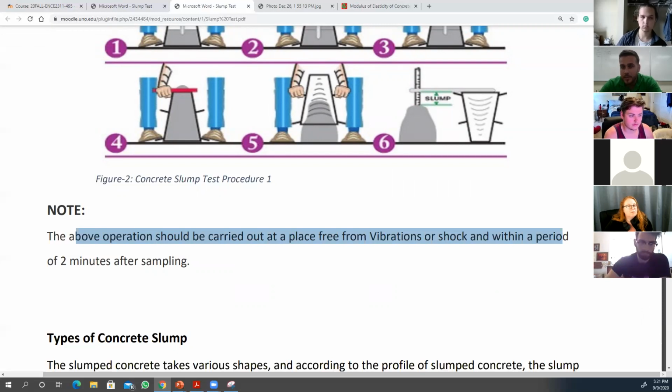We don't want any space in the concrete because if there is any space somewhere here in the cross section, my area was 28.3 inch square, right? If you sum those gaps, and let's say it is 1 or 2 inch square, 28.3 minus 2 inch square is 26.3 square. Divide 1,000 pounds by 26.3 and look at the strength. Does that make sense? Okay.